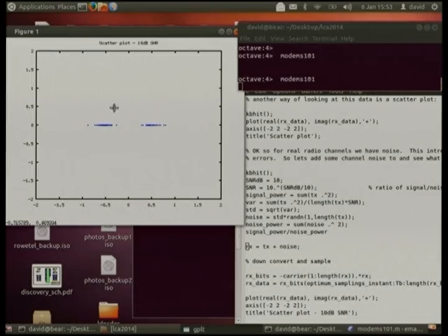So as the signal to noise ratio drops, the spread in the scatter gets bigger, and eventually you start generating bit errors. A good modem will have fewer bit errors for a given signal to noise ratio than a bad modem. So that's the scatter diagram showing us the effect of adding noise to the radio channel. And at 10 dB, you can still see there's no bit errors there. None of those have even got close to the middle line, which is pretty good for digital communications.